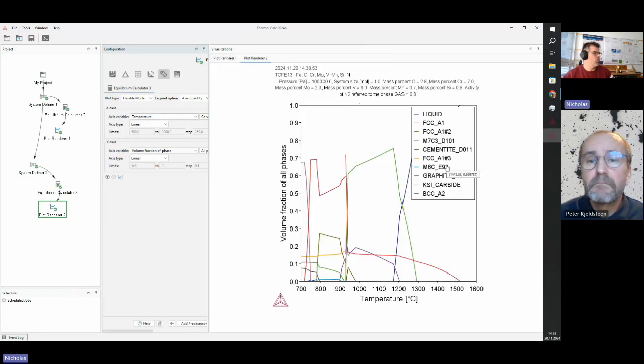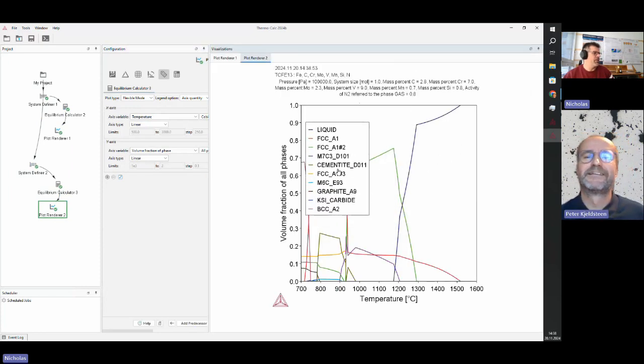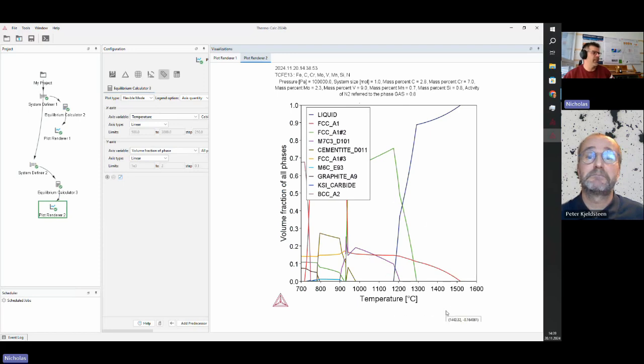Okay, so don't worry about the low temperature, I'll hide it here a bit because these are mainly numerical things that I would have to figure out. I also see graphite forming, right? No, exactly. And this is typical. Even in a normal steel, graphite is the stable phase, right? But that would be a typical phase that you actually have to remove from the calculation.